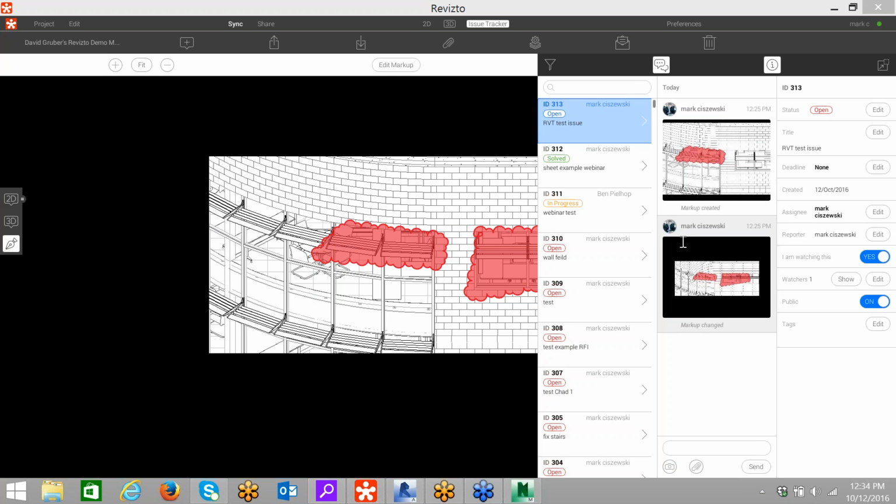So in terms of the optimization, the way it works is that the project is exported directly into Revizto as the original format. From there, you can select the optimization quality you'd like to push out to your team. Once optimized, you need to select sync, which you can see highlighted on the top left of my screen right now. And what that does is it allows you to select that quality.